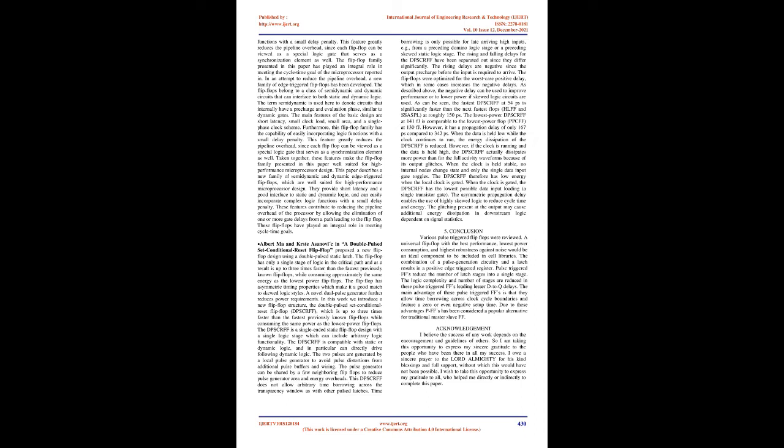It allows integration of logic into the flip-flop, as well as reduced clock swing operation. A single-ended input version with multiplexed data scan and asynchronous reset is possible. The new flip-flop uses a new output stage latch topology that significantly reduces delay and improves driving capability. The performance of this flip-flop is verified by measurements on a test chip implemented in 0.18 µm effective channel length CMOS. The demonstrated speed places it among the fastest flip-flops used in state-of-the-art processors.